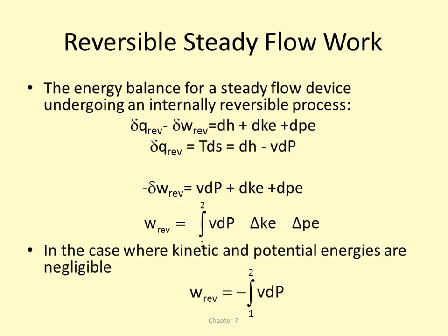So del Q, we plug that in, this simplifies. So our reversible work for a steady flow device is equal to this V dP. And in general, we neglect the kinetic and potential energies. So this was how we determined the reversible work for a pump or a compressor.